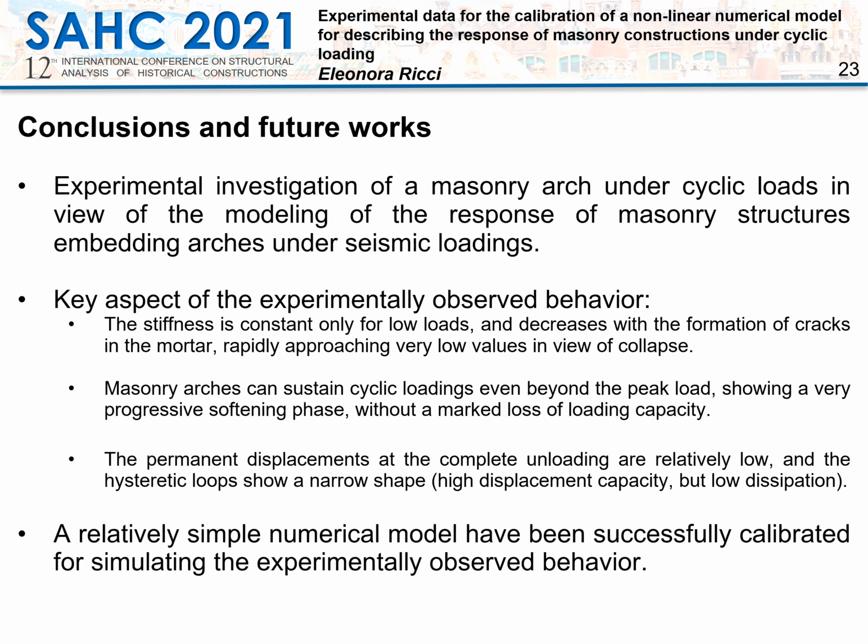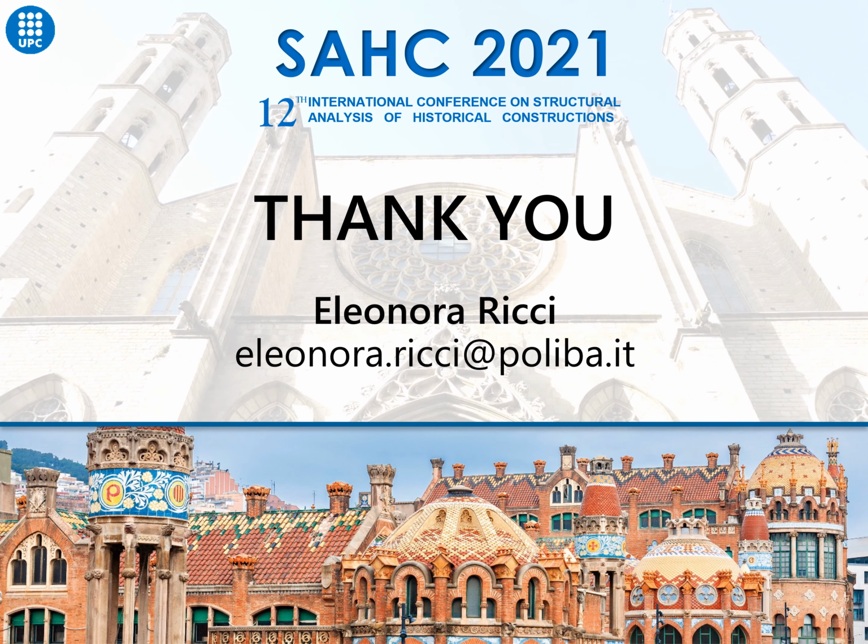Second, masonry arches can sustain cyclic loadings even beyond the peak load, showing a very progressive softening phase without a marked loss of loading capacity. Third, the permanent displacements at the complete unloading are relatively low, and the hysteretic loops show a narrow shape, characterized by high displacement capacity but low dissipation. And finally, a relatively simple numerical model has been successfully calibrated for simulating the experimentally observed behavior. Thank you all for your attention.